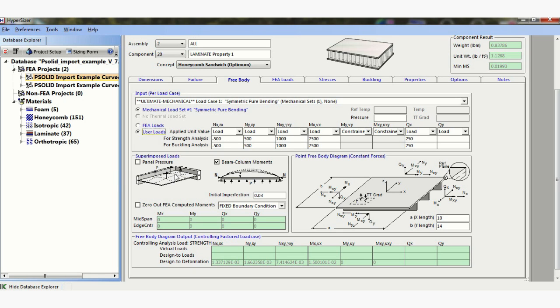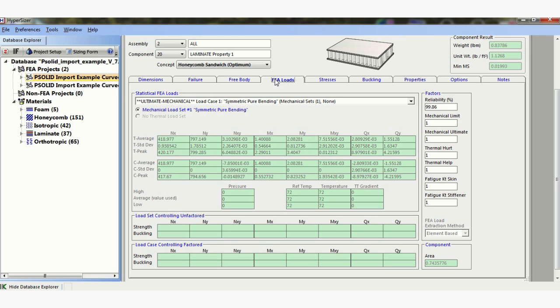There's some things here that kind of bother me, especially this panel pressure. When we put pressure on here, in reality this plate doesn't bend. It's in membrane for most aerospace structures because it's too thin. If the displacement's bigger than the thickness, it's a membrane structure, so it's pulling on this stiffener, but it's also adding a bending moment to this stiffener, and depending on whether we put simple supports or fixed here, or even simple supports along here, it makes a difference. And I only have part of the solution here. I'm pressing something, but I don't really know what I'm going to get. So I just think there could be a lot more clarity here.